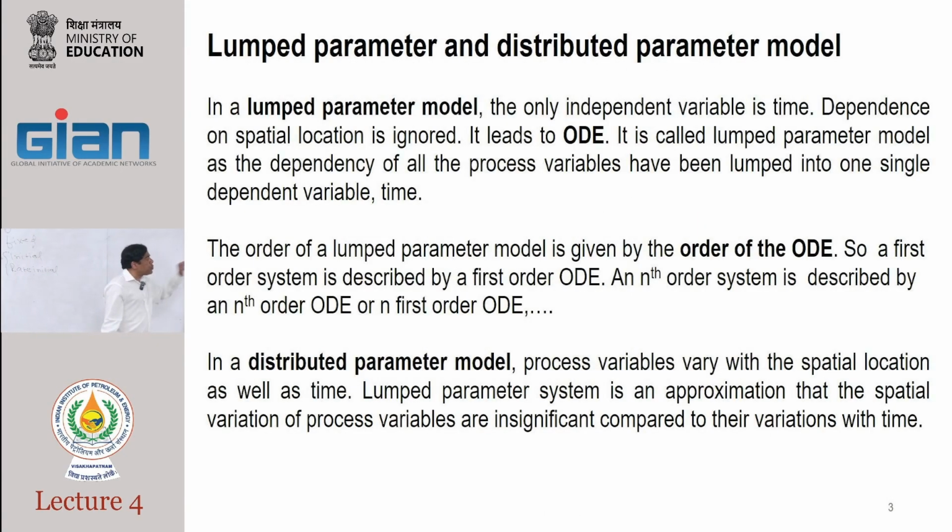Now in the distributed parameter model, the process variables will vary with spatial location as well as time. When you think about an adsorption bed, and we'll be discussing this more, something comes in and the adsorption front keeps moving forward. So the front keeps going forward through the system. So this is actually a distributed system.